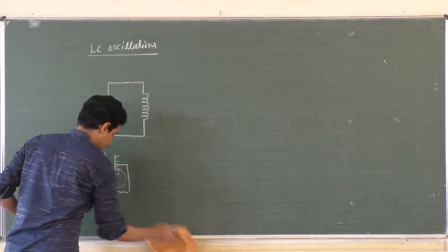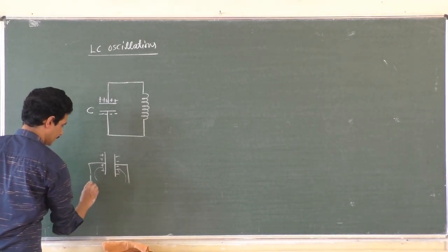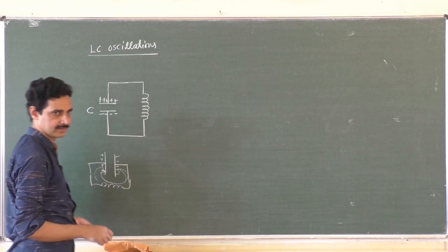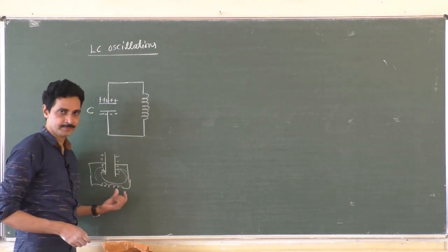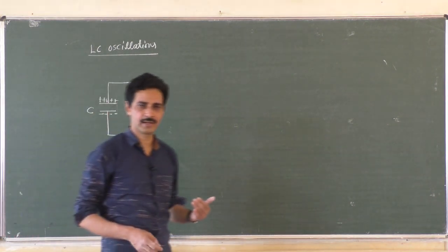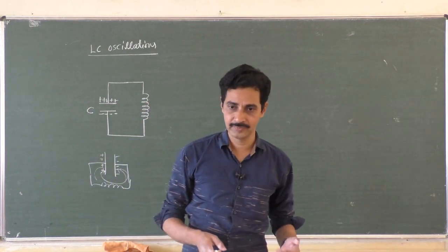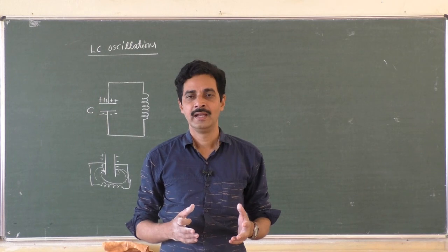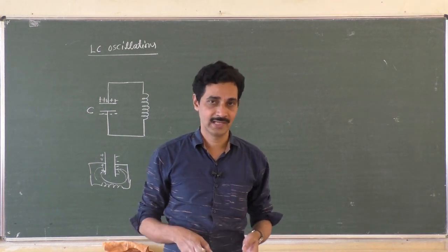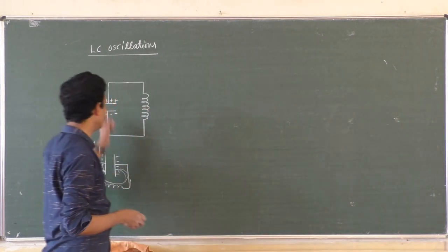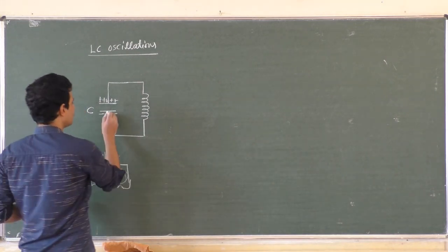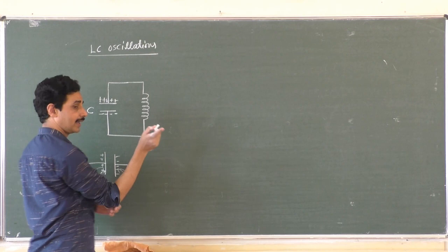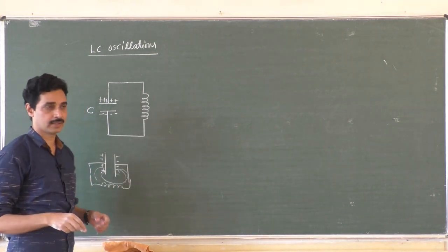Now, the battery has been removed and this is connected across a coil. Now these electrons have got a chance of going back, even though this opposes, because when the charges flow through an inductor coil, there is a variable magnetic field. If the magnetic field varies, then that change in flux induces a current which opposes the change, right? But still, electrons can flow. They got a path. As the electrons flow like this, there will be a current like this, right? Because current direction is taken opposite to the direction of electron flow.